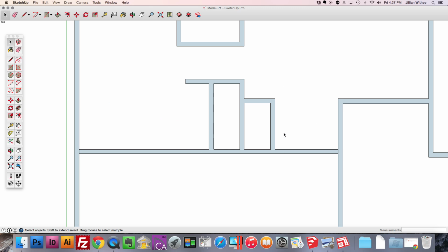For this wall group with this face, the closed loop starts here and runs all the way around. If we delete that one little line, the face disappears and we no longer have a closed group. That's why we can't delete the intersections between the exterior and the interior, because this line closes this group of interior walls. It's not shared with this exterior wall.